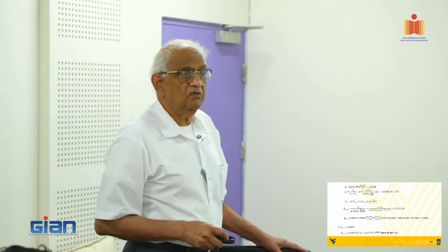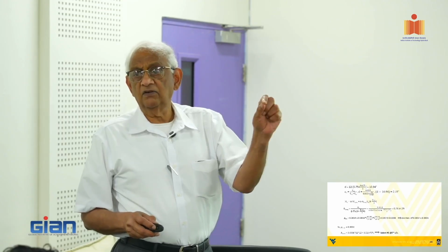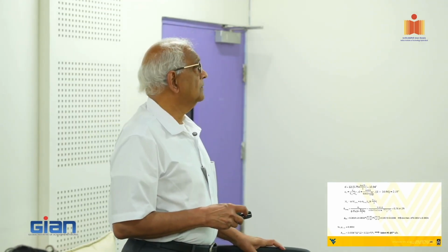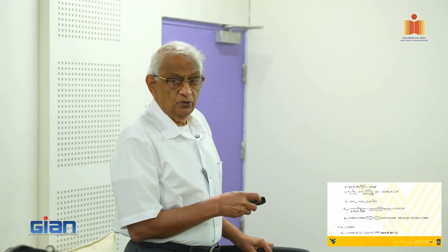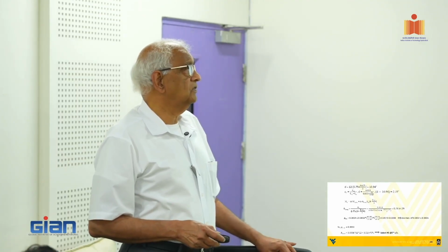Beta 1 is, what is beta 1? If it's a 4,000 psi concrete, beta 1 is 0.85. If it's a 6,000 psi, beta 1 is 0.75. Yes, like that. So F sub FU, we already talked about it, 72 KSI. That is F sub FU. So anyway, from there, that is what we got. What we need is 0.26 square inch per foot width of your slab as the amount of reinforcement needed.